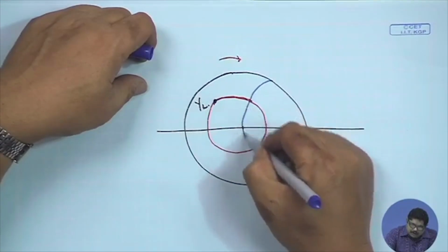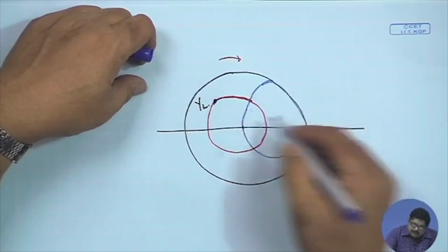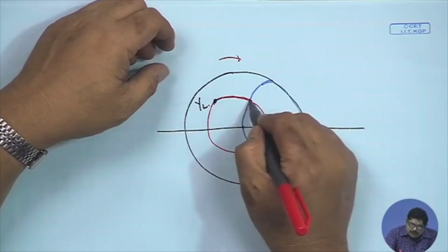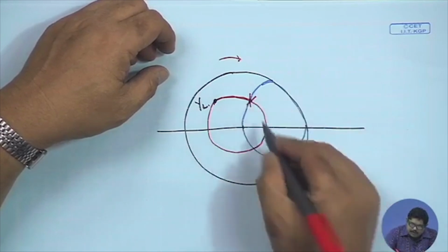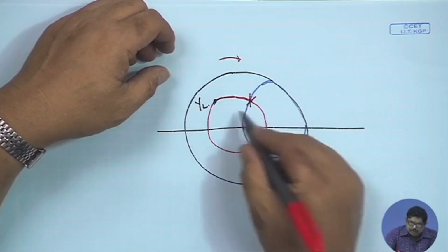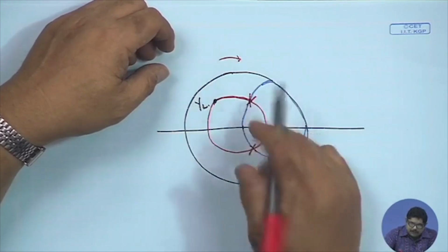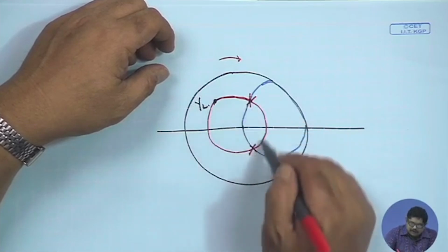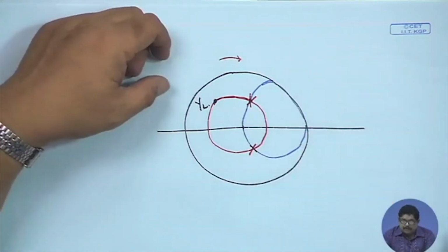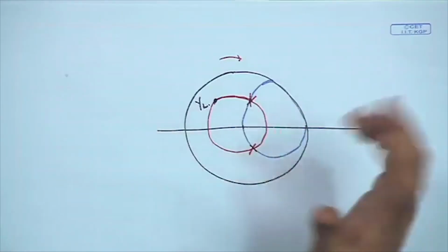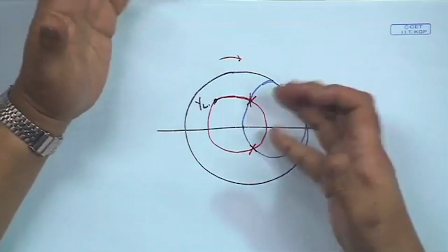This is the constant conductance circle, let us say, in the Smith chart. So, there I can come. Here I can either come to this point or I can continue and come to this point. So, these are the two solutions. Now, it is up to the designer, because the frequency response of these two solutions will be different. So, from the frequency response you can decide which one you will take. Also sometimes construction difficulty etcetera can tell you.